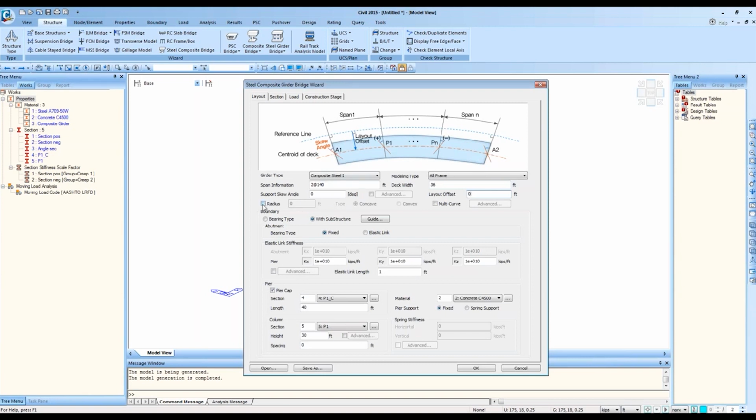The radius. If your structure has uniform curvature radius, you can simply click on this number and just change the number here. But that's not a common case. Unless it's a perfect ramp structure, all the structures have varying radius, or you might need to reflect the vertical elevation change or super elevation change. In that case,